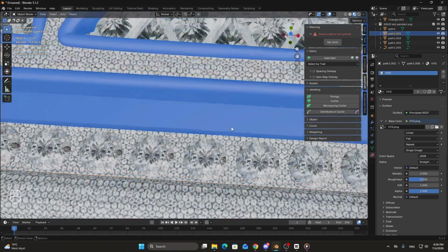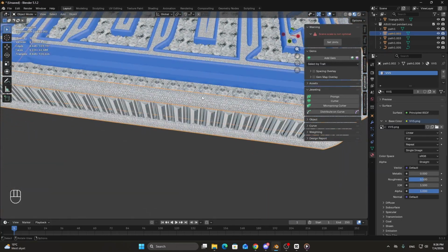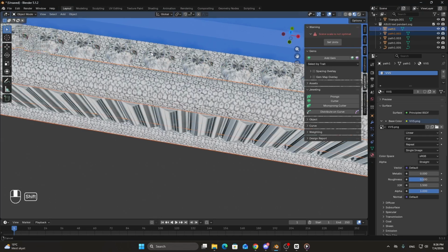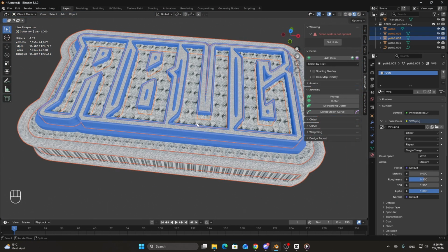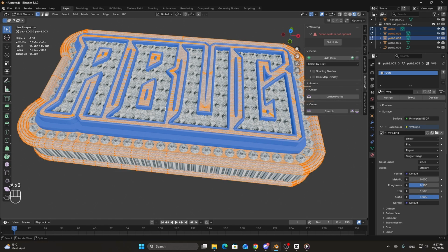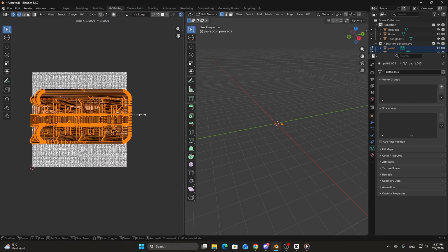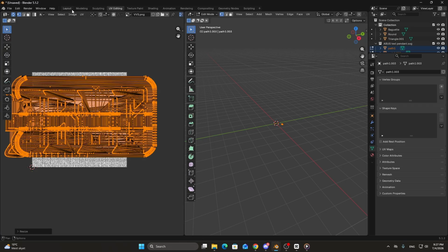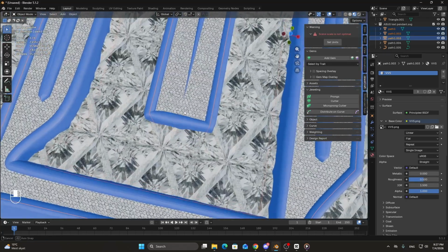And as you can see, I think I want these diamonds a bit smaller, so I'm gonna select this, shift click this one, and this layer, and then press Tab, and then press A, so it's all selected. Go into UV editing. Important to have this one checked on. Then S, press 1, 0.5. Then the diamonds are a bit smaller. This size is a lot better.